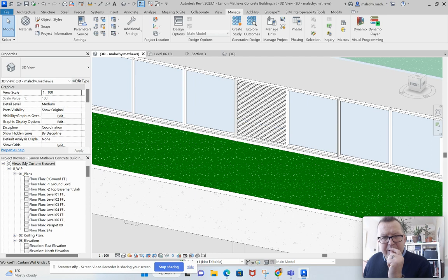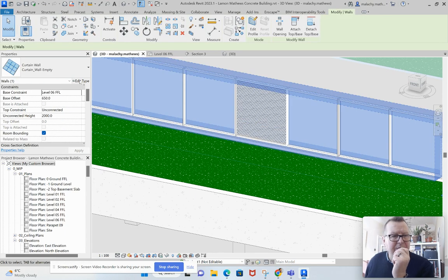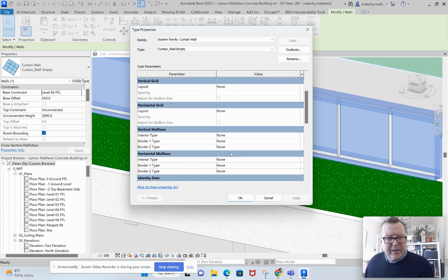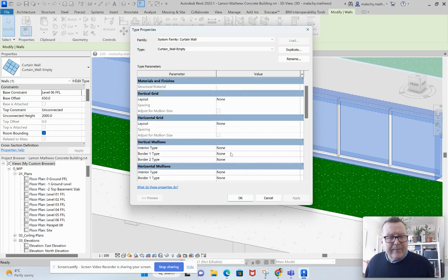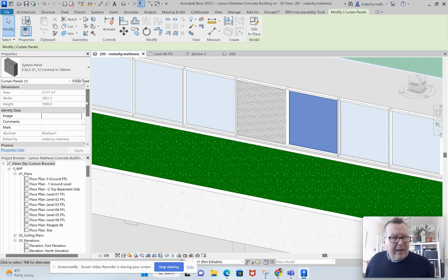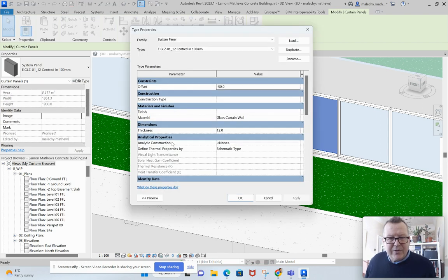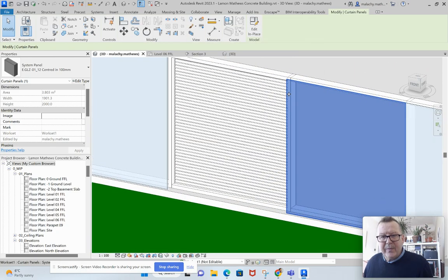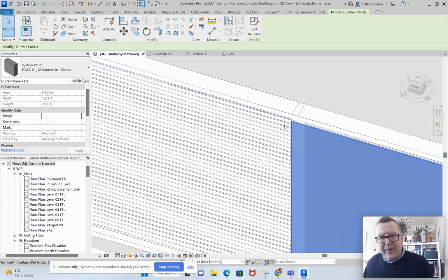The other thing I might do here is go into the properties of this. I've got a layout across here. I'm going to show you how you can do these quickly as well. Oh, it's in the panel. So if I pick the panel here, and again, I pick the next door panel, I think there is a parameter here for offset. See the offset? So I'm going to offset that 150 and see how that works out. Apply. Good. Now, what that's done is that if I zoom in here a bit, I'll show you that it's brought that panel forward a piece.